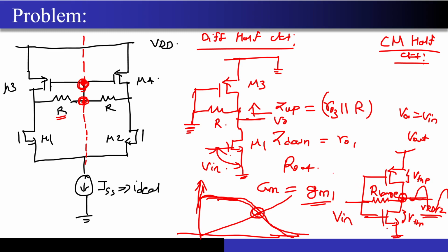Okay, yeah. So what I was saying is, I was just trying to give you an analogy that we had looked at one similar circuit where we had inserted this resistor. So now the thing over here is, if I had not inserted this R large, then the DC point at the output is poorly defined. What do I mean by poorly defined? Just look at what is setting the output biasing point. The VDSAT, the overdrives of these PMOS and NMOS transistors, correct?